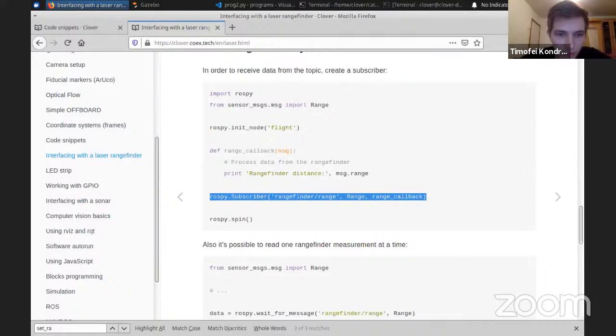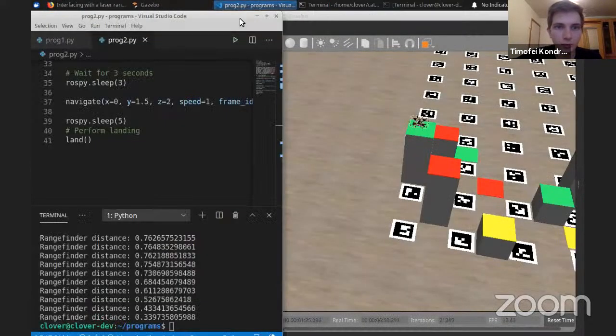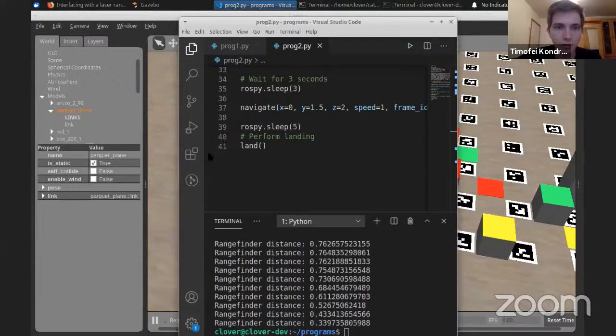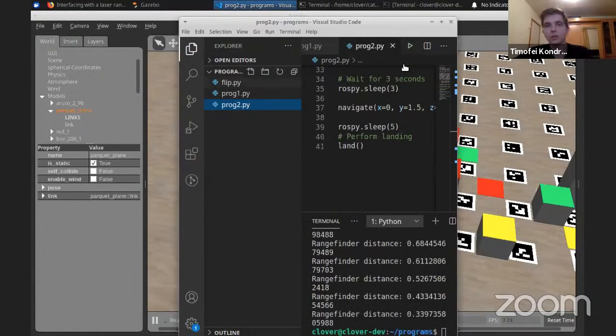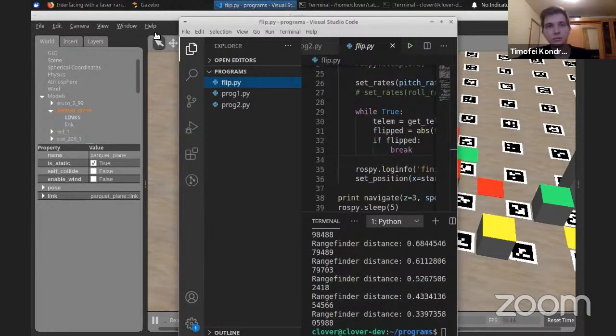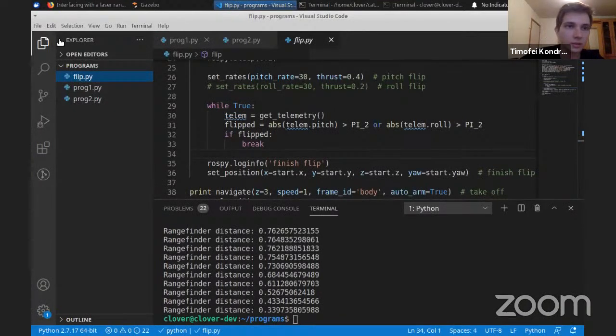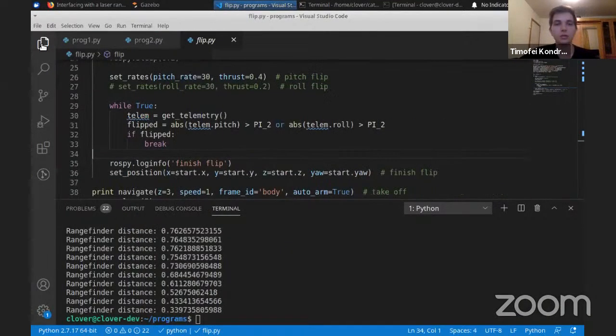Oh, does the change made in simulator affect the flipping in real drone? Well, flipping in simulator will be performed differently than in a real drone. So, for example, if you try to use these parameters on a real drone, the real drone might fall instead of doing a great flip. So I don't recommend you just blindly copy and paste flip from simulator to a real drone. For the real drone, the default configuration of the flip was tested and worked fine.